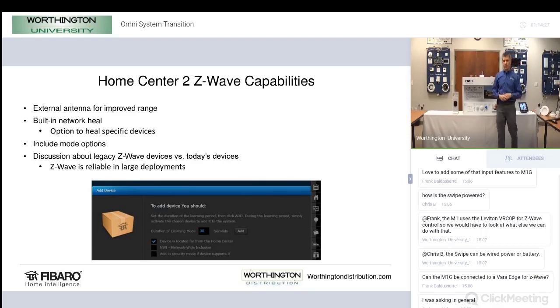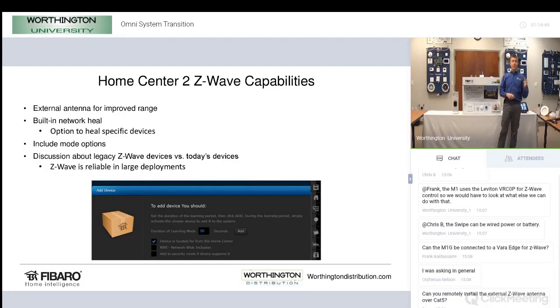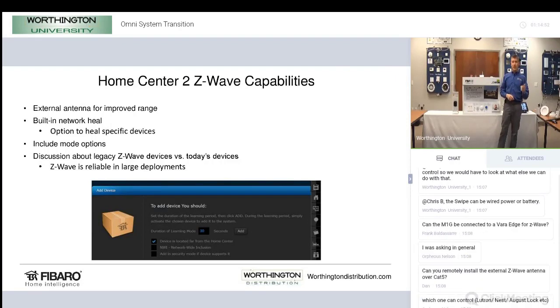So one thing that happens with Z-Wave networks, depending on what level of Z-Wave you're using and how different things work, it is possible that as you start to add devices, the more devices you add, the more robust and reliable that network will become. The issue, however, is if you install, say, 50 devices, the 50th device knows about everybody before it, and it knows how to communicate through all those devices to range extend and to hop and everything else. The first device, however, doesn't know about 2 through 50.